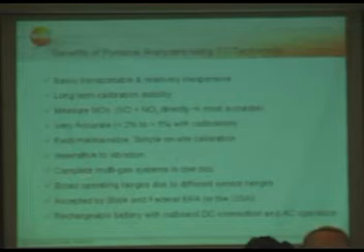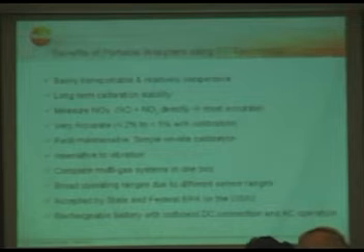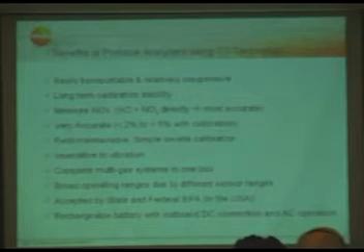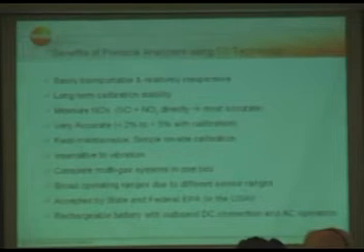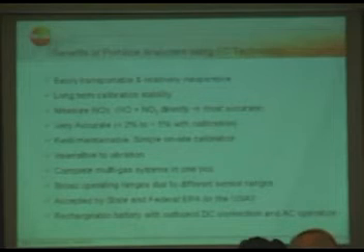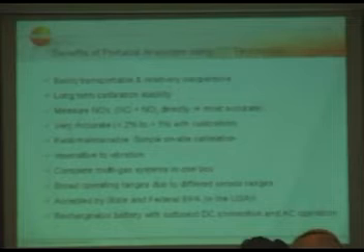Yes, you have a complete multi-gas system in one box. That means you can measure up to, in our case, 6 parameters simultaneously, which in some cases is not possible if you are using reference technology. That means you have one analyzer measuring CO, one measuring NO, one measuring hydrocarbons, and with electrochemical sensors you have more parameters within one box, and you can, of course, cover many applications with one analyzer.